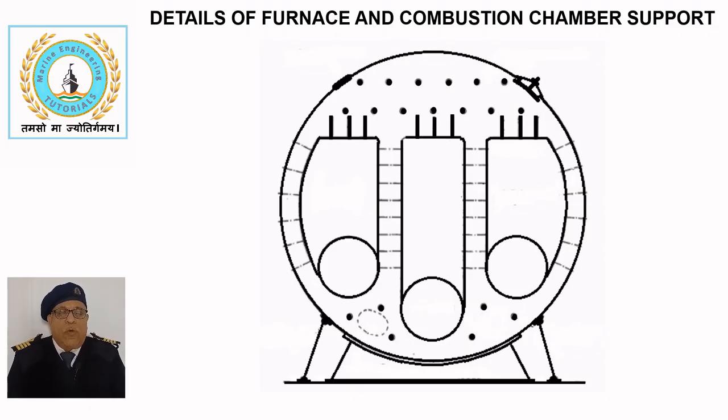When a boiler is used for high evaporation rate, the furnace size must be large enough to generate the required volume of flue gases. However, increasing the furnace diameter requires greater wall thickness to withstand the higher stresses, which in turn reduces heat transfer efficiency. To overcome this limitation, a multi-furnace boiler, as shown in the figure, is designed to deliver high evaporation rate with improved efficiency.